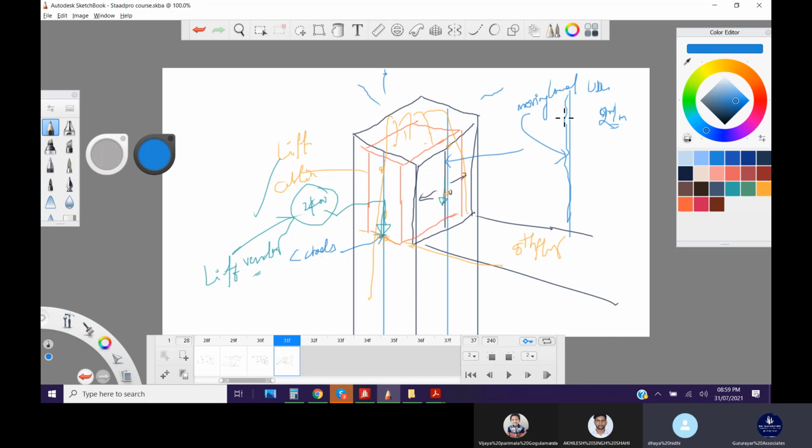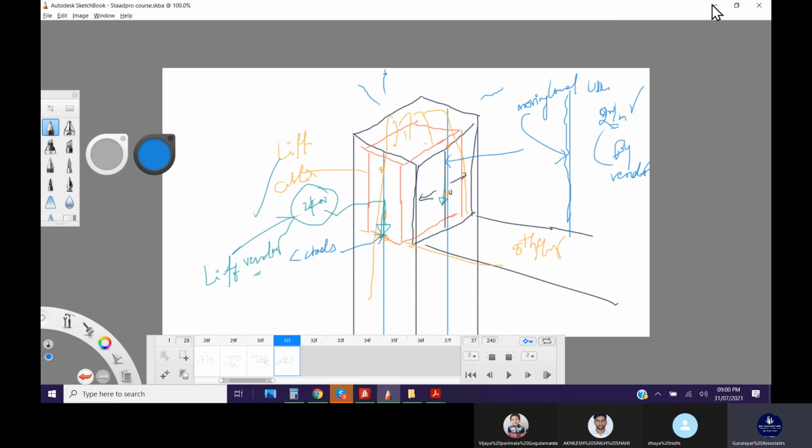So moving load, even though it is designed by the vendor, you will design the size of the channel. But this channel's moving load reactions, or any effects of this moving load, will be applicable to this wall also. So generally, this UDL load we have to apply on the centroid of the wall also. Let us use this 2 kilonewton per meter and apply it centroidally. You see what happens. So this 2 kilonewton and 2 kilonewton per meter wall, both we will try to apply in this model.